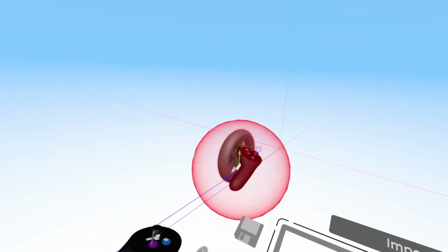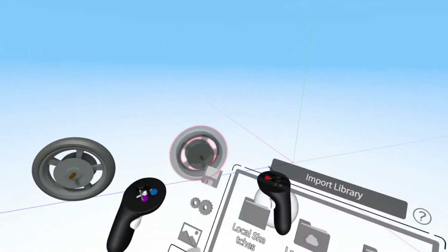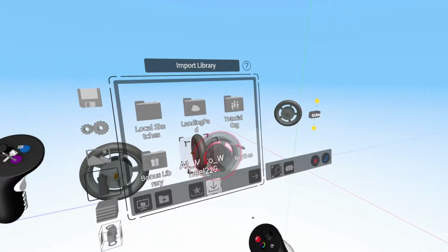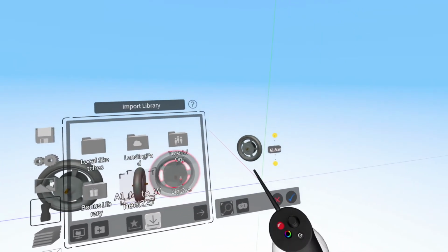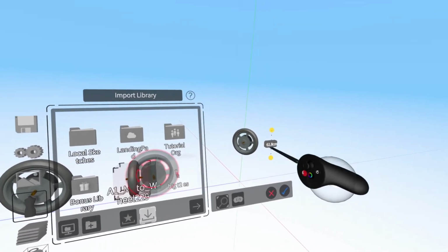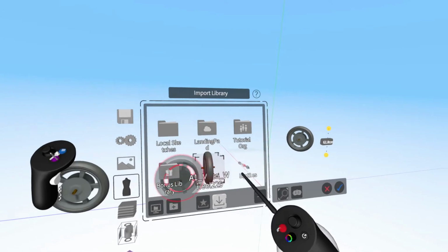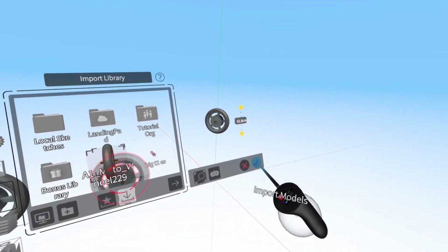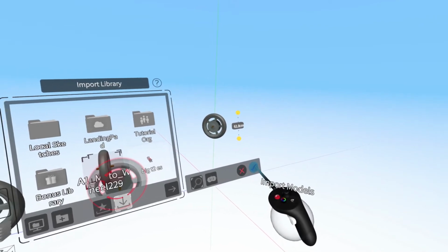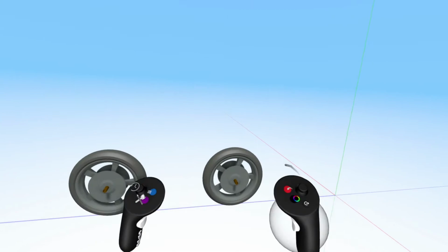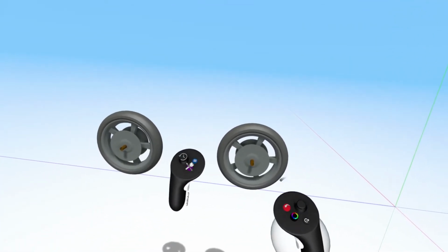If the objects were created in Gravity Sketch, they will load in at the same location they were created at, at the same scale. For other file types such as OBJs, you will have the option to scale and orient the files in the preview window as well. Once you are ready to confirm the import, press the blue check mark in the corner of the preview window and your file will be placed in your scene. One important note on using this method is that files created in Gravity Sketch will retain their layer structure.